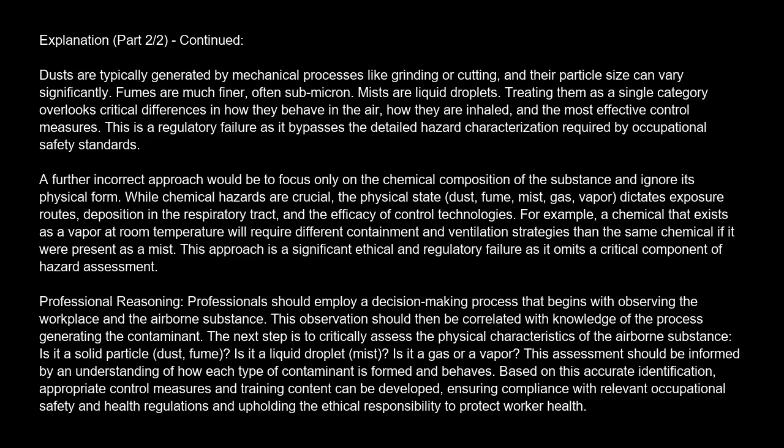This approach is a significant ethical and regulatory failure, as it omits a critical component of hazard assessment: professional reasoning. Professionals should employ a decision-making process that begins with observing the workplace and the airborne substance. This observation should then be correlated with knowledge of the process generating the contaminant. The next step is to critically assess the physical characteristics of the airborne substance.